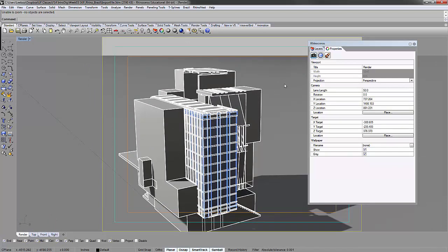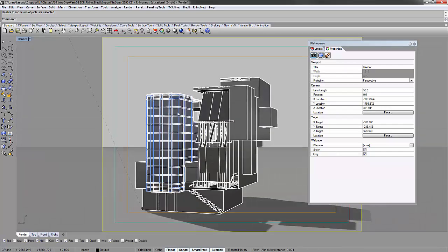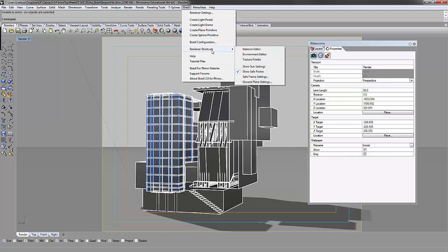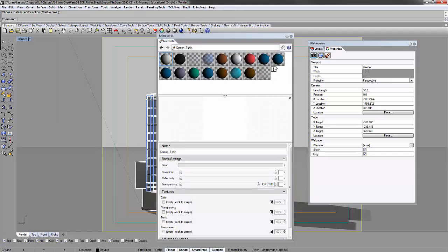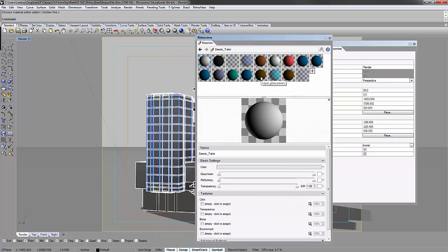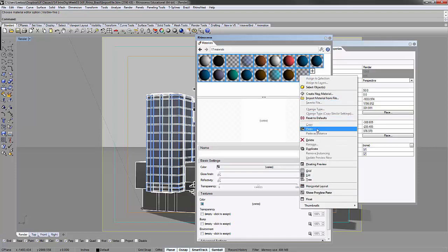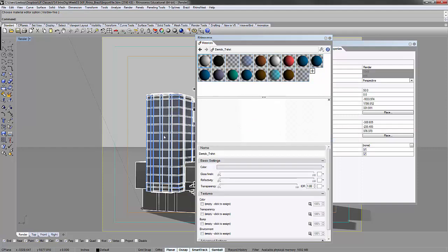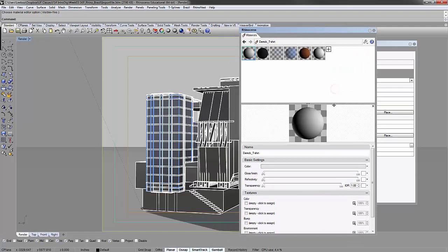So you'll see that we try a couple tactics. If we're looking at this file, let's just say we want 3 different materials: a white, generic gypsum or stucco, diffuse white, a wood color, and a glass. So if you go to the material editor here, a lot of these are coming in with the SketchUp file, and you can basically try to ignore them. You can't actually delete them all, because a lot of them might be used by the blocks or component instances. Some of them you might not be able to delete outright, basically anything that's still in the scene.